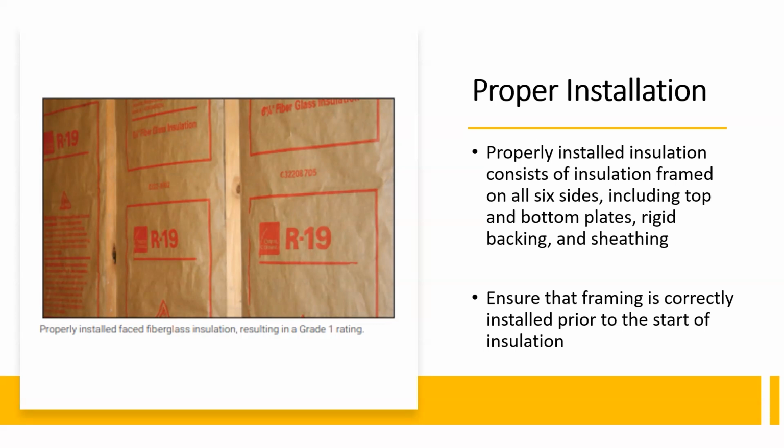Yeah, you're right, Cody. The most common confusing thing lately is double walls. Thankfully, we talked about last week that it's being addressed in the 2024 code. But double walls, common walls, demising walls in townhouses being split, having that fire break that's there, you've got the gap between that. It's not fully insulated. It's not fully sealed. Or, as I talked about with a walkthrough, having a double wall at the back of a media room because you're hiding 2 flue pipes and all your media drops, and then you're just netting all of that and not even capping it at the top.